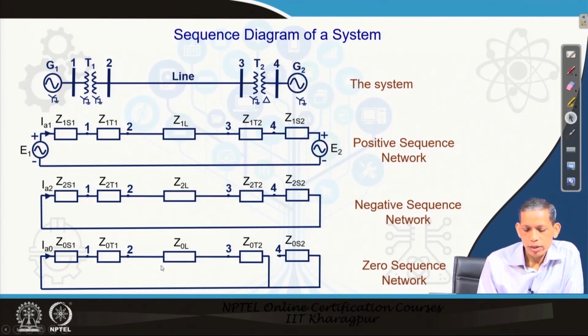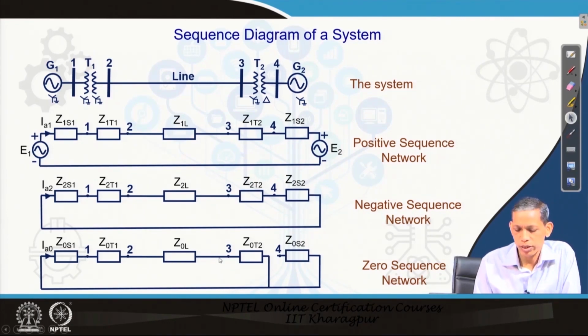For the right side transformer T 2, one side is delta connected, so circulating current will be there. So, that is connected to the reference in this perspective, and this is not connected to the source side because of the delta connection on the line side, where the zero sequence current will not flow. Therefore, the corresponding zero sequence diagram becomes like this with the associated zero sequence impedances.